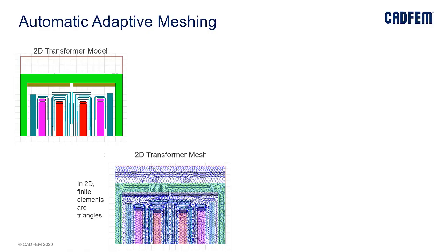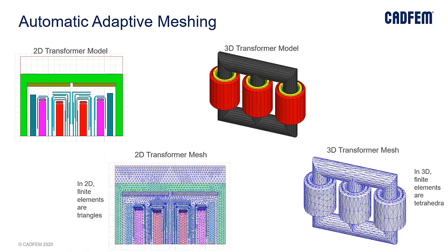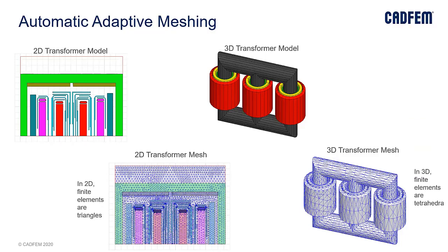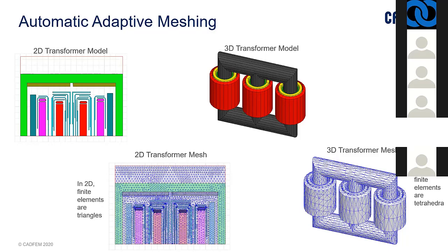It's not a tough task, because even if you don't know anything about meshing, the solver will automatically create the mesh for us. The only thumb rule is that it is always better to create equilateral triangles on the mesh if it is 2D. Whereas if it is 3D, if you can have proper tetrahedrals over the mesh, then it would be fine enough. That is the basic idea to represent the mesh. But the beauty in Ansys is it will automatically create the meshing for us, because as we are not mechanical engineers, we are not good at meshing. So the Ansys electromagnetic solver will help us to create the mesh. Hand over to Dhanuko. Thank you, Hara.